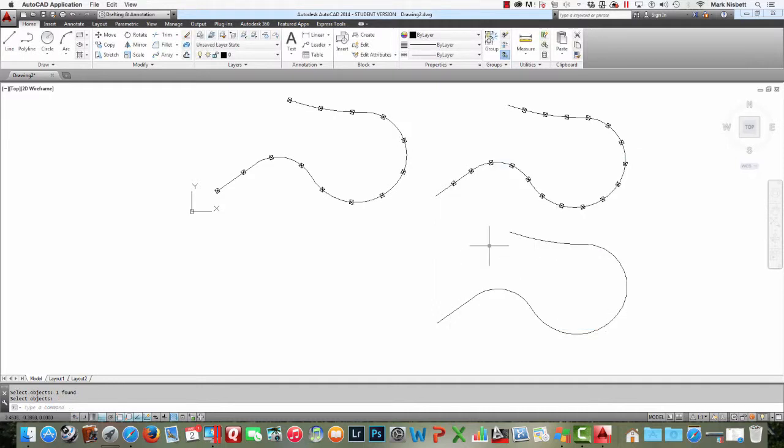And this time we'll do measure again. We'll select it. Block. We're going to use track. Align it this time or not. We'll say yes and see what happens. 0.25. Okay, so you can see how it's drawing it like that.